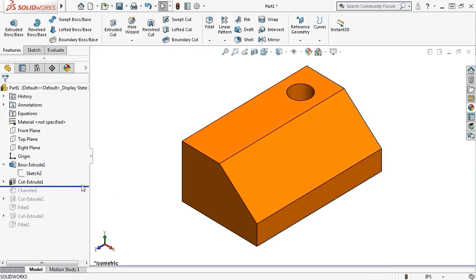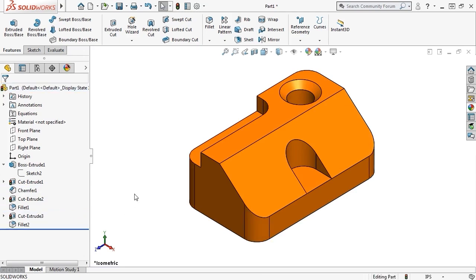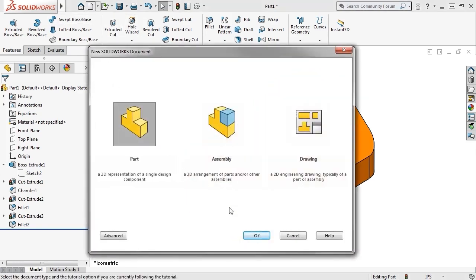Following the first feature is a through hole, a chamfer on the hole, an extruded cut, and a fillet to round out its edge, another extruded cut, and another fillet feature used to break the corners of the part. Notice that compared to the through hole and the rectangular cut, this cut is an interesting case. The other cuts go into the face perpendicularly, while this cut does not. We'll take a look at how you can accomplish a feature like this when you don't have a very obvious face or plane for a sketch. Let's start a new file and walk through the step-by-step process of creating this part.